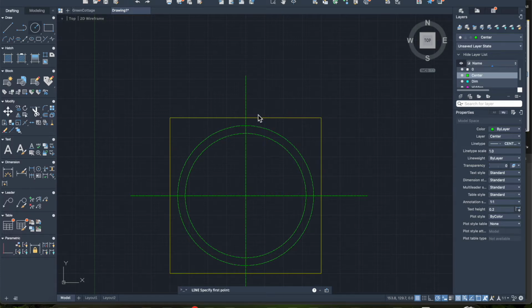And because we're only concerned with half of this, just this one half here, instead of the entire piece, 20 divided by 2 gives you 10. So your line, your solid line, is going to start 10 millimeters in from the edge. So what we want to do is get our line tool, make sure that we are on the objects layer, click on the corner, and then type in 10.